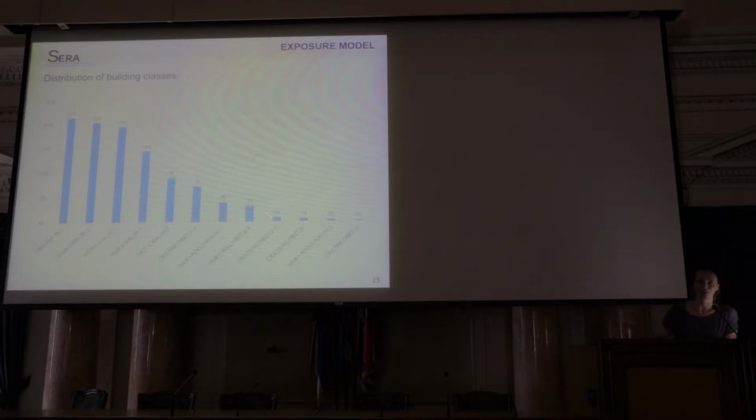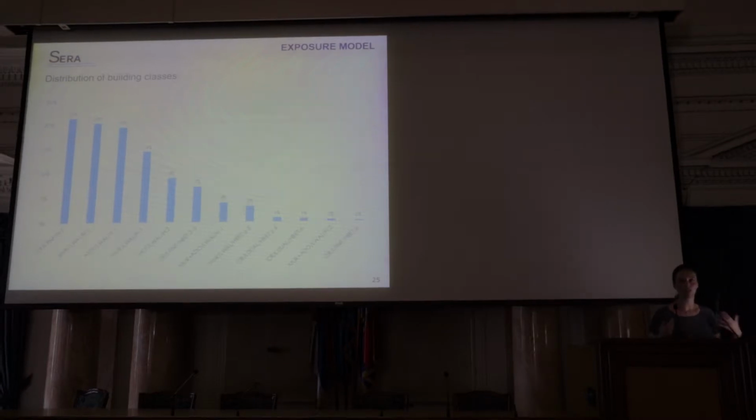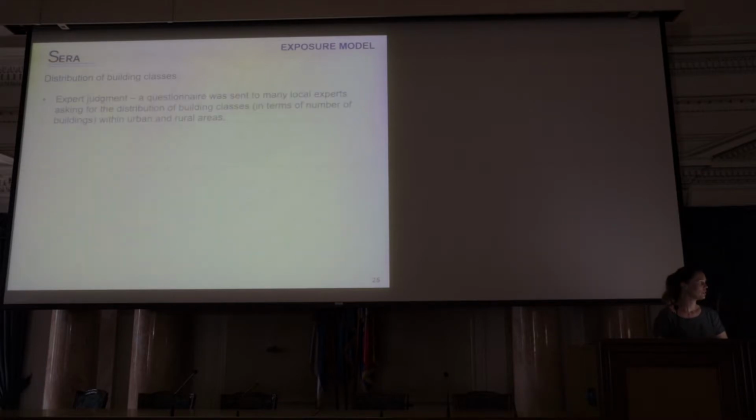How do we get this distribution? The information in these building classes is not typically available from those national publicly available sources of data. The census does not tell us the percentage of reinforced concrete frame buildings with infills of 3 stories. They might tell us the percentage of buildings of 3 stories, or the percentage of buildings built before 1960, or with concrete or unreinforced masonry as an external material, but we don't know for sure that masonry is the lateral load resisting system in that case. So we need to develop this distribution of building classes through a number of different ways.